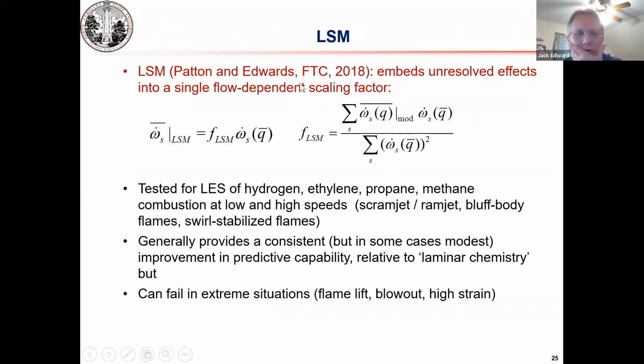So what is LSM? This is something we developed a few years ago, and it's a very simple closure. You start with laminar chemistry, multiply it by a flow-dependent factor, and then you get your model for the filtered production rate. The model F_LSM is shown here. It's essentially a least squares minimization of a functional that describes the reactivity.